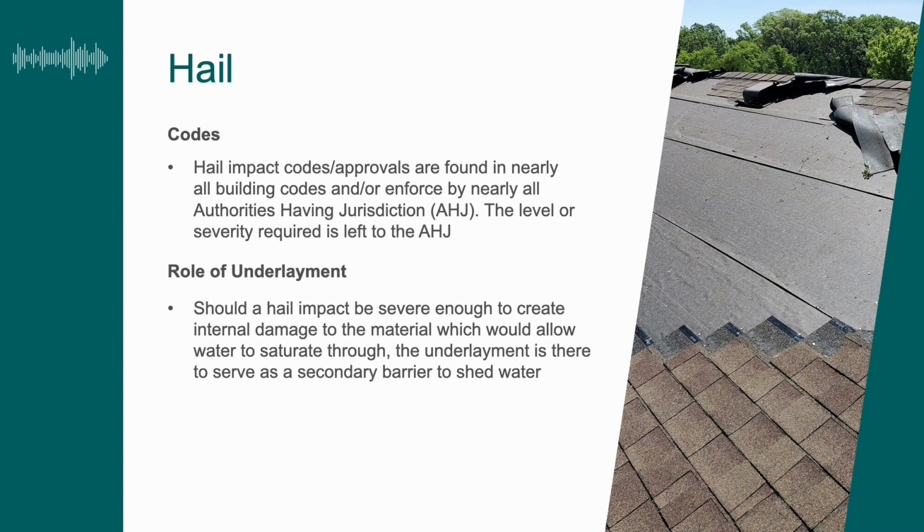Talk about codes for a second, okay? Pretty much any product you're going to see in the markets, with a few exceptions that I can think of, from any major manufacturer, has been tested for hail, and that's pretty clearly outlined. Now, there are some elements that will have specific requirements. You'll hear the term authority having jurisdiction. Whatever city, county, or state it may be, you need to double check with that authority having jurisdiction to see what severity they require.